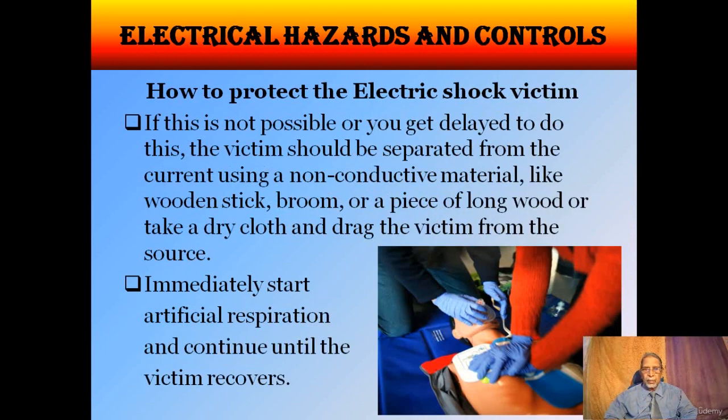If this is not possible or you get delayed in doing this, the victim should be separated from the current using a non-conductive material like a wooden stick, broom, or a piece of long wood, or take a dry cloth and drag the victim from the source. Then immediately start artificial respiration and continue until the victim recovers.